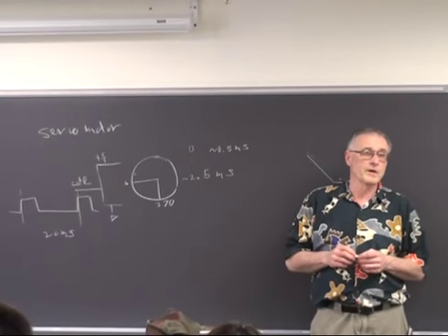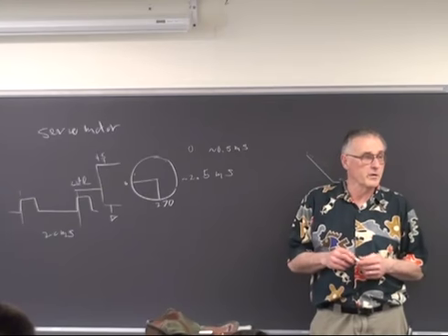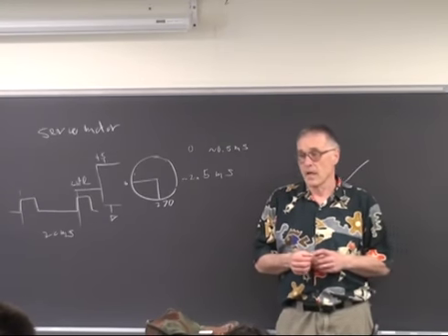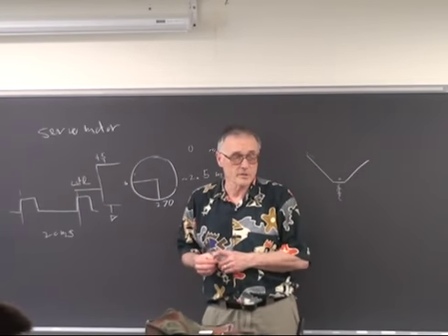So if you need to move, say, an atomic force microscope around, you use a piezo actuator because you can get submicron accuracy at very high bandwidth and very high force.